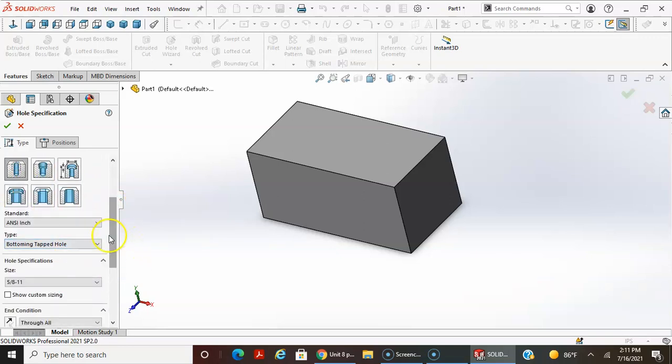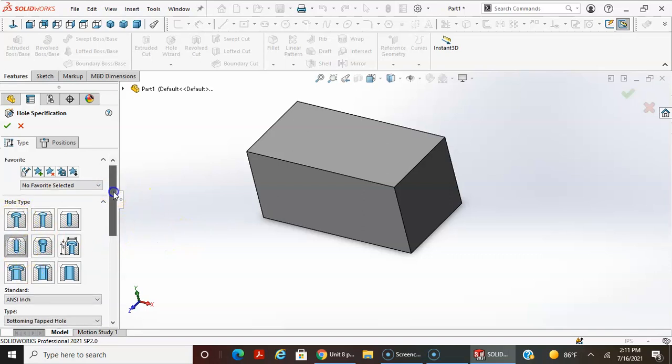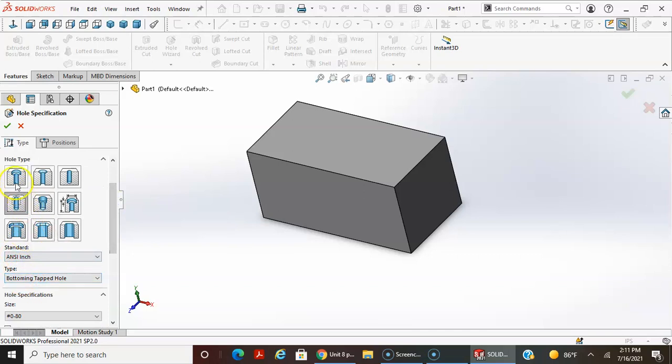And you can see within the property manager, the area is gray. If I bring my mouse into the graphics view area, it shows what is selected is grayed out, the background. And what that does is if you look down here, it changes the rest of the property manager for the hole. So I'm going to select straight tap.